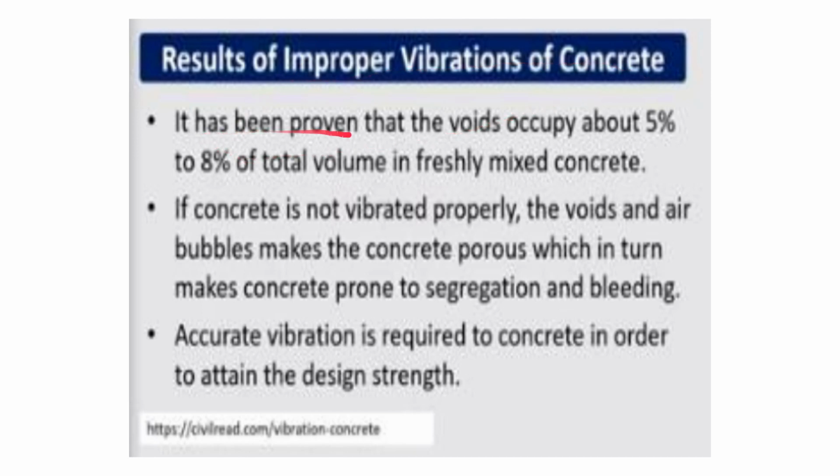Now let us see the results of improper vibration of concrete. It has been proven that voids occupy about 5 to 8% of total volume in freshly mixed concrete. If it reaches 10%, as we studied, the compressive strength will decrease by 50%. So that is why it is very important.